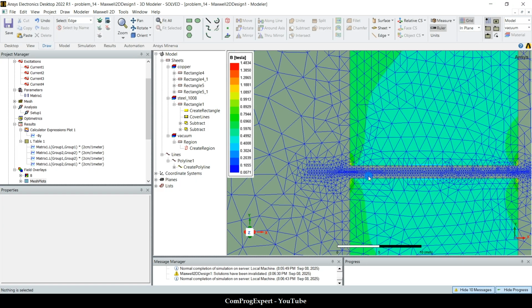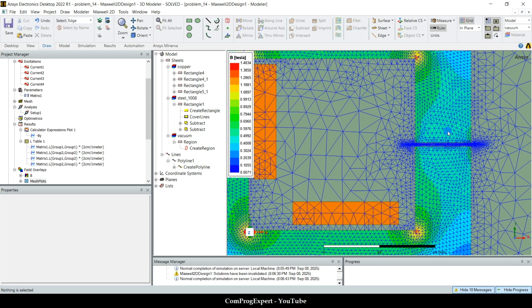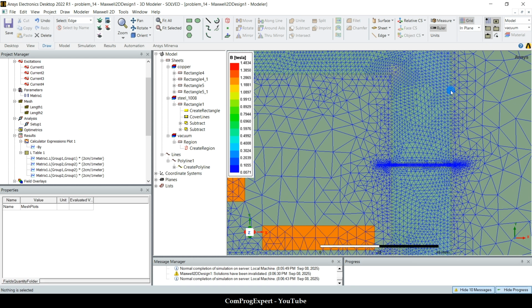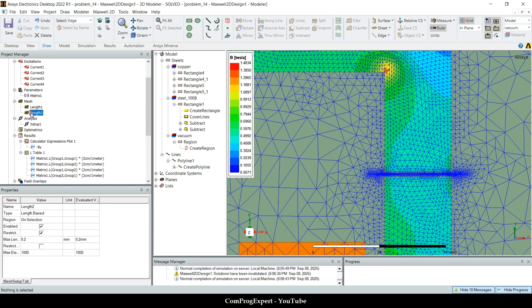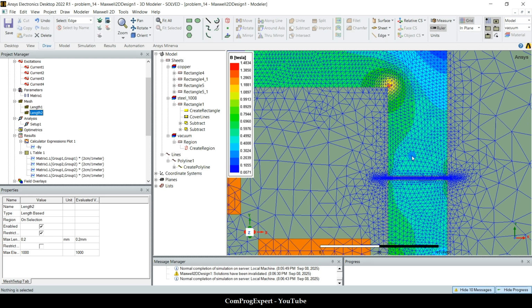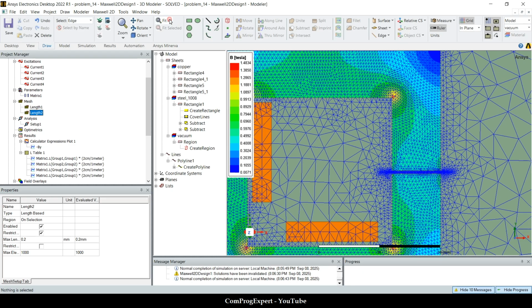Yes. So now you can get a good idea about what the finite element software do. Why I reduced the size of triangles in the iron for a more accurate solution? Because I wanted to consider more reluctances. Okay, so this size is good, and we can calculate the magnetic field with a good assumption. You can consider other sizes also.